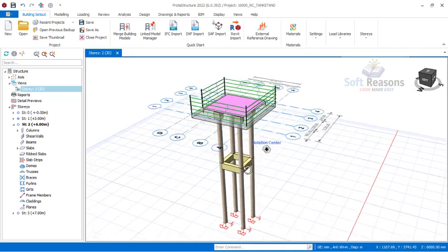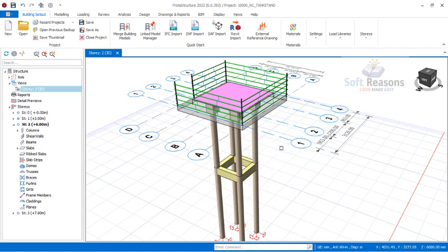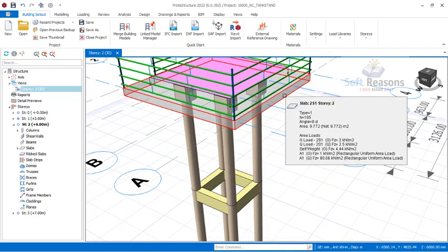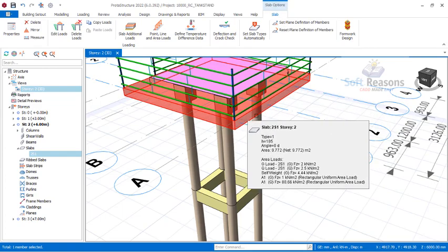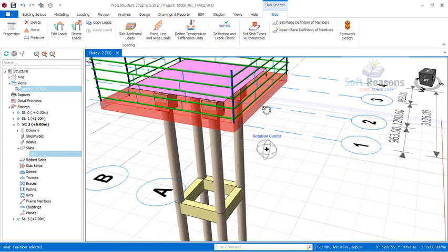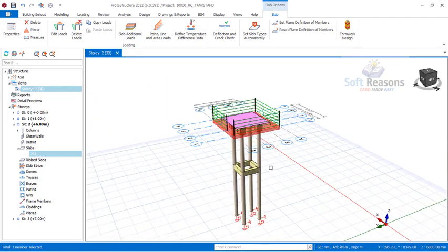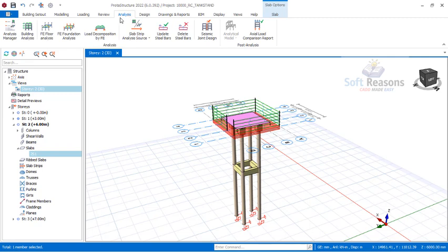At this point we will be carrying out some check on the structure. Mind you, this is going to be designed using the finite element method of analysis to design the slab, and then we will mesh the load with the columns so it can be sent to the foundations for the foundation design successfully. At this point we will go to the building analysis tab right there, and at first we will be performing a static analysis, building analysis. Over there, static analysis, you select that on the building analysis provisions.